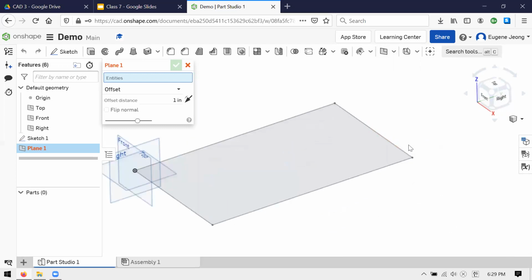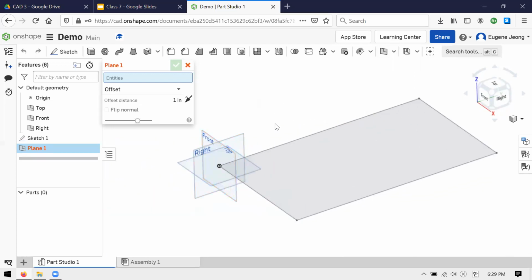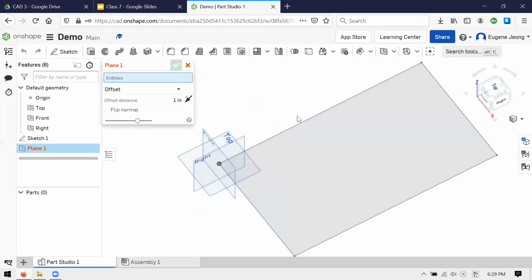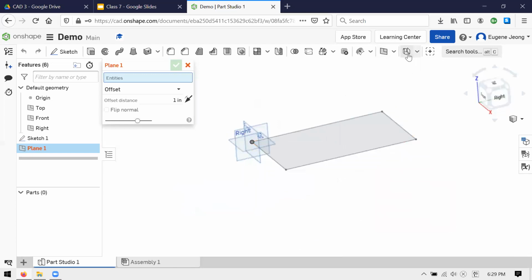We have talked about references before, but we may not have really used them. Something that's very useful in CAD is what's called a reference geometry. You already have fundamentally these 4 reference geometries: the origin, the top, the front, and the right plane. These exist in your CAD, but they aren't actually solid things that you get out of your CAD.